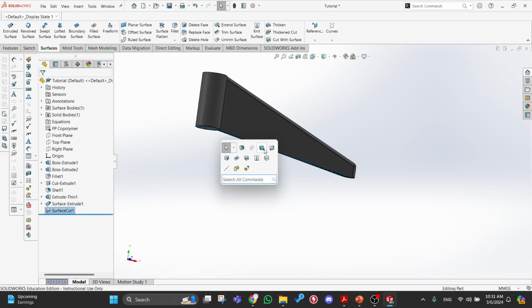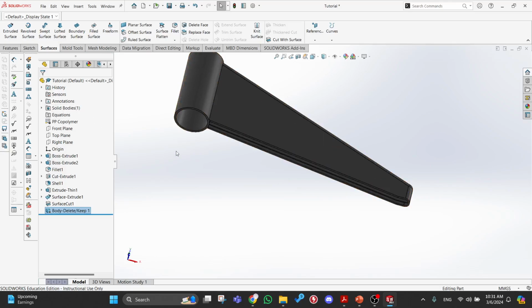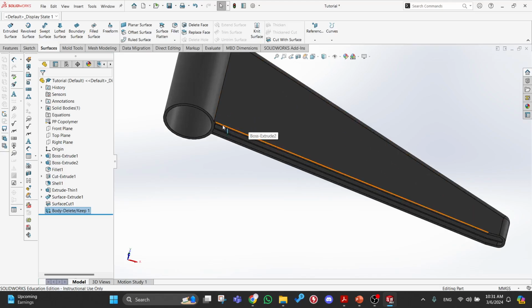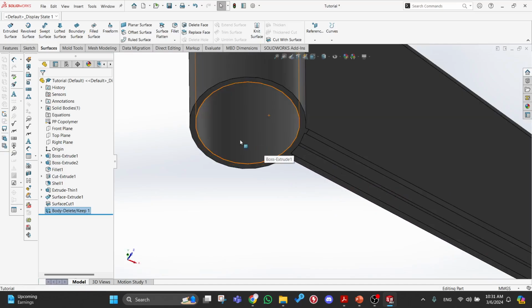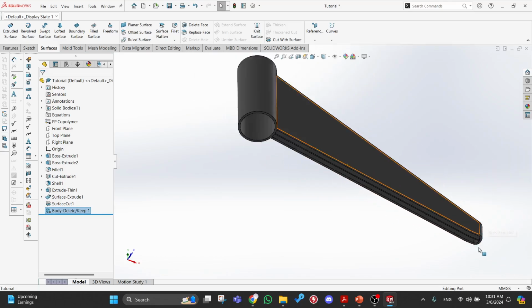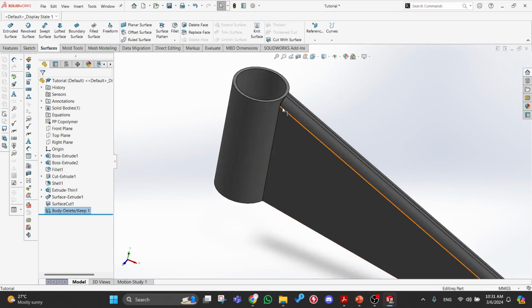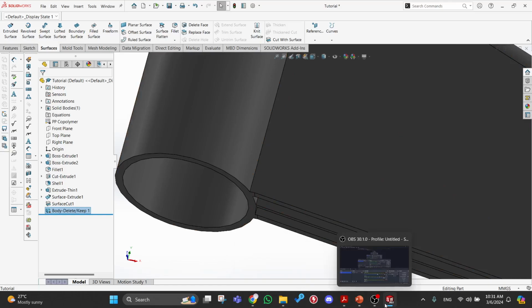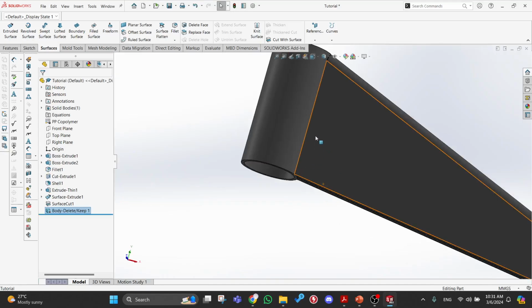Okay, then this one you want to delete your surface bodies. You do not want any surface body, because when you do your static FEA simulation later, if you have any surface body with no thickness, they don't know how to calculate that and just refuse to work, right? So this one is straight up, because later our force is going to be static, going to be here, so there's going to be an infinitely rigid point, and then this point is where the force is going to be. This is important because if it's connected like this, it won't spread out the force to the side, right? So this is to exaggerate the effects there.